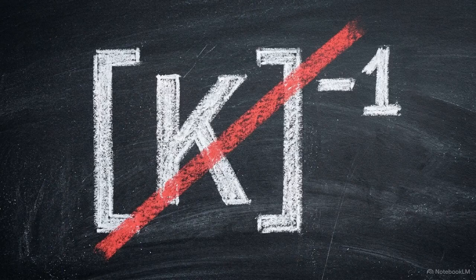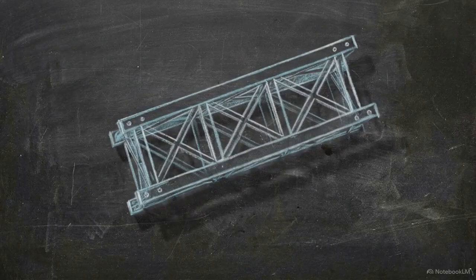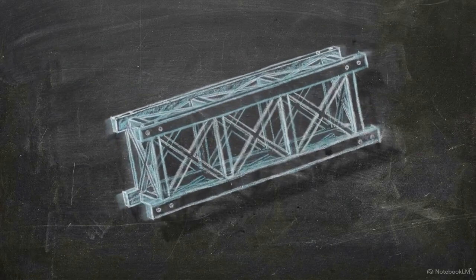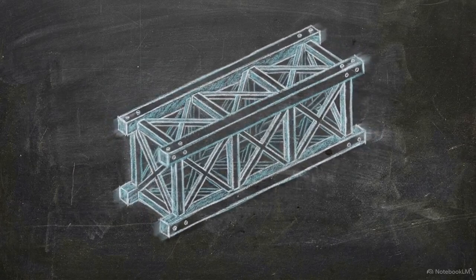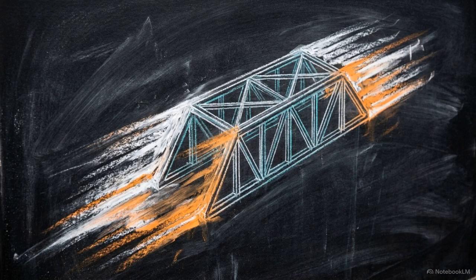However, this global matrix cannot yet be algebraically inverted to solve for deflections. Mathematically, this is because the model lacks anchor points. We have defined the structure, but we haven't bolted it to the ground. Without constraints, the system undergoes rigid body motion. Any applied force will simply accelerate the whole structure indefinitely through space.